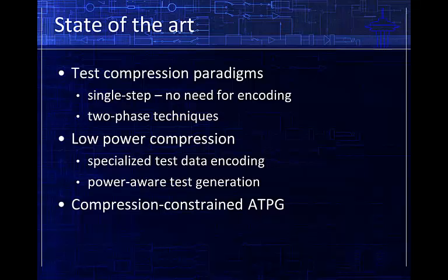In two-phase methods, such as various reseeding techniques, ATPG generates a test cube without any knowledge of the decompressor, and then we try to encode it by solving systems of linear equations. The decompressor typically has much higher encoding capacity, so the encoding works for arbitrary test cubes. The other major advantage of the sequential decompressors is that they can be reused as PRPGs in compression LBIST hybrids, which have recently become very popular in automotive applications.